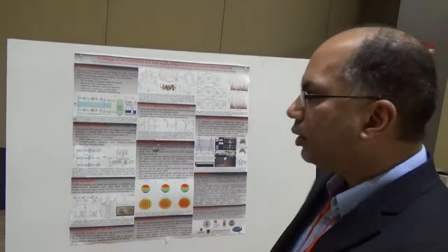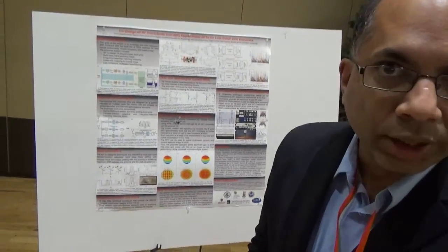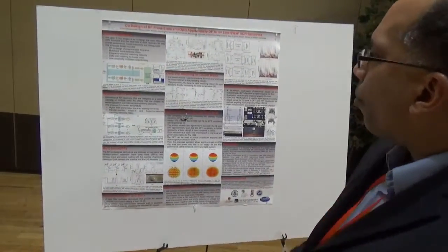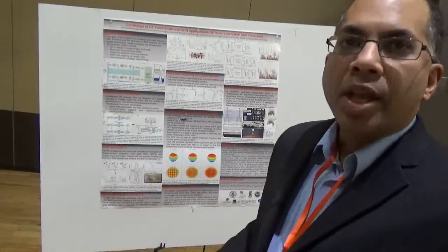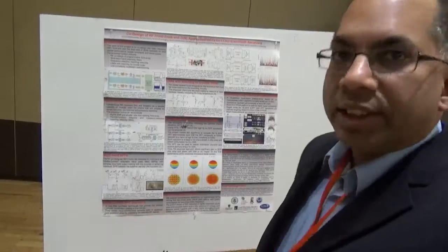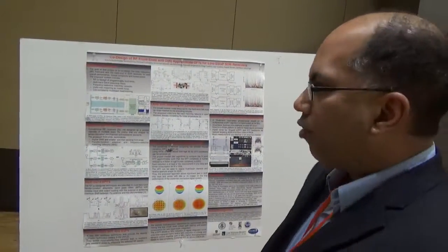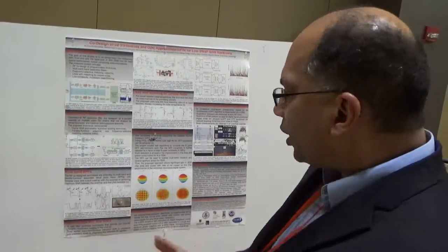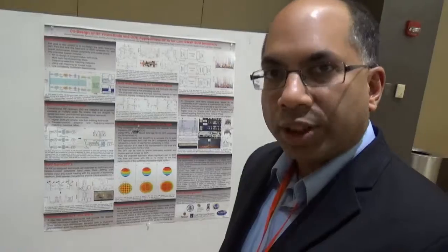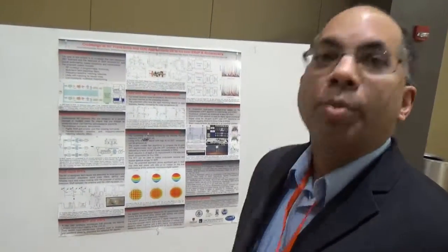Given the imperfections, the question is, can we now quantify that and redesign our front end so that these imperfections don't have much of a role to play in the final performance? So we optimize the low noise amplifier (LNA) using wideband matching and noise matching to get the best sensitivity. Then we include some tunable filters for optimally removing interference. So we optimize all the microwave front ends as much as possible, and then we estimate for that optimum front end what the bit error is.